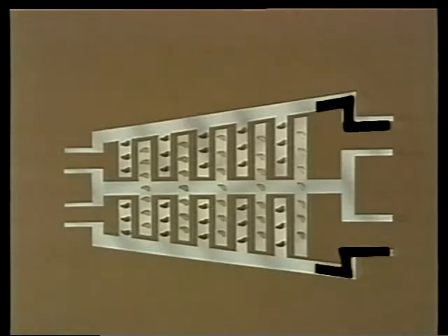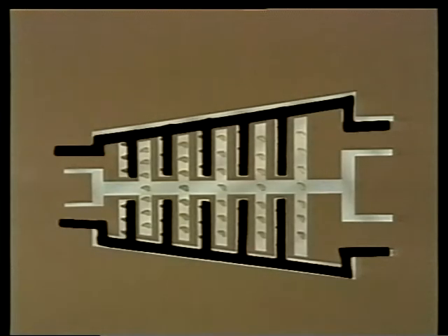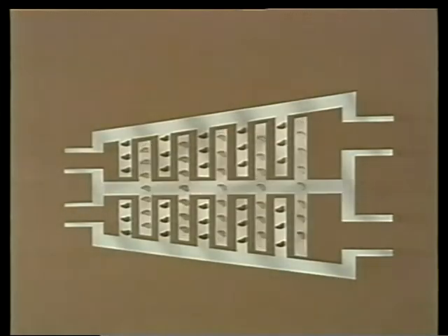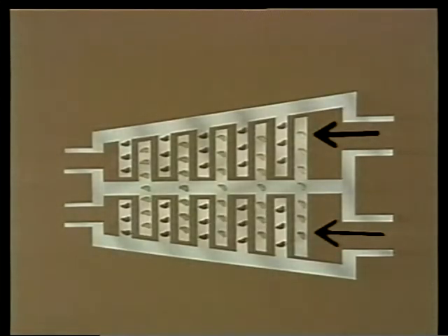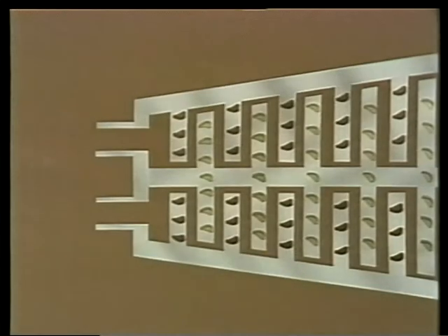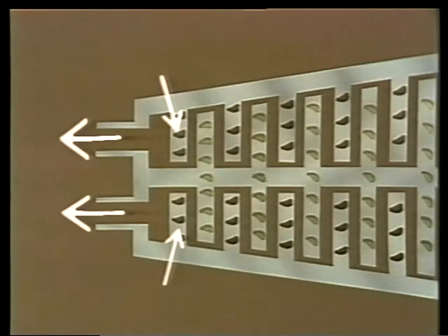An axial compressor has a tapered shell and fixed stator blades, and a shaft with spinning rotor blades. Air enters the compressor where the shell is widest. The rotor blades act like fans that push the air down the length of the compressor. Now, since the stator blades don't move, they direct the air flow and provide some resistance that slows the air down, causing pressure to increase at every stage. After the last set of stators, where pressure is the greatest, the compressed air flows out into the discharge piping.